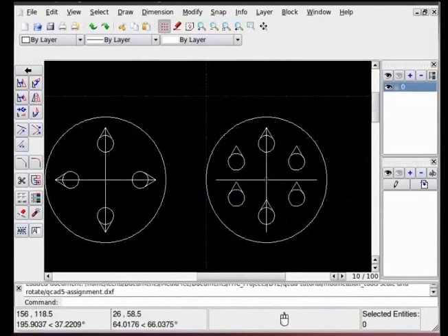Now see the difference. Since I had given angle B as minus 60, it has become 0 and objects are arrayed in circular direction but without the rotation for individual objects.